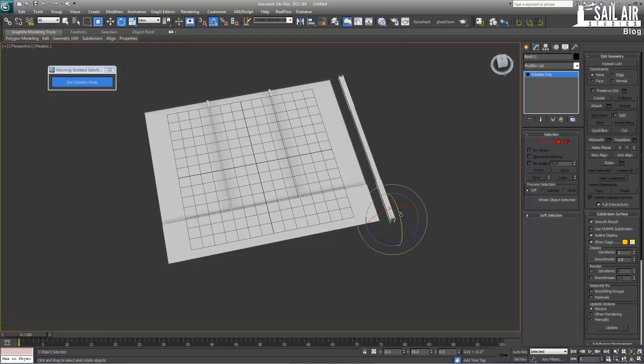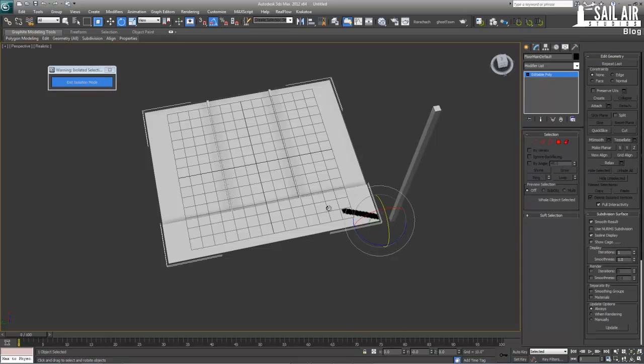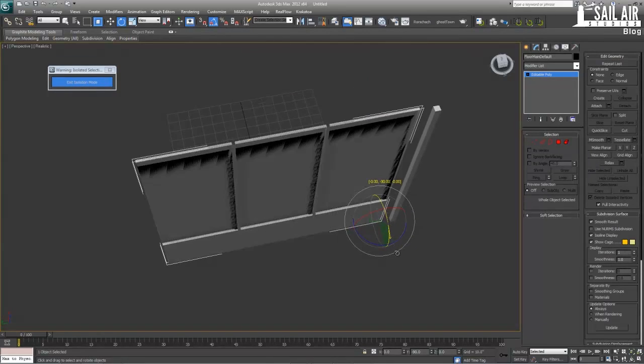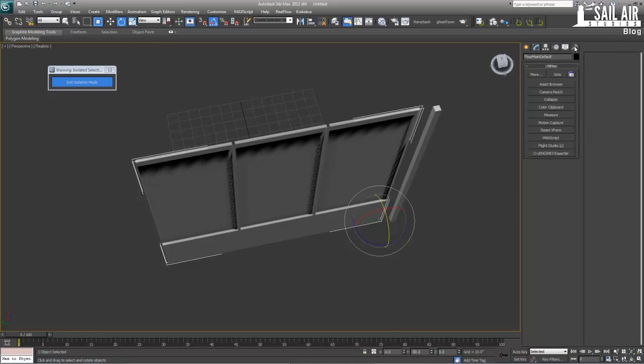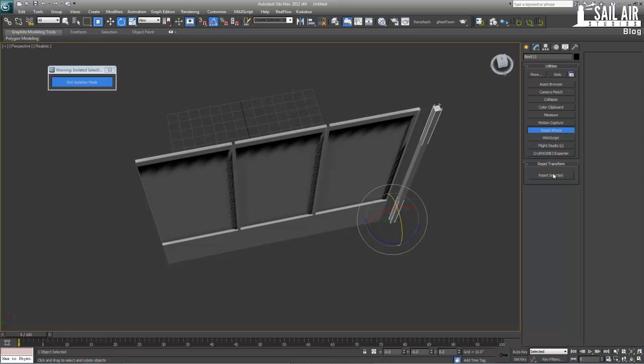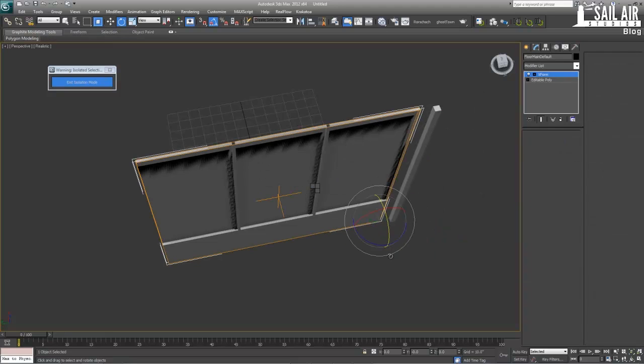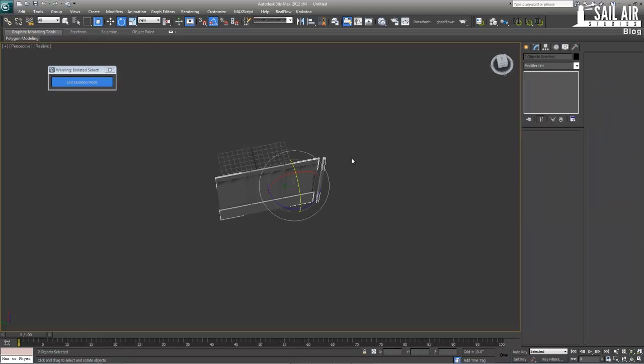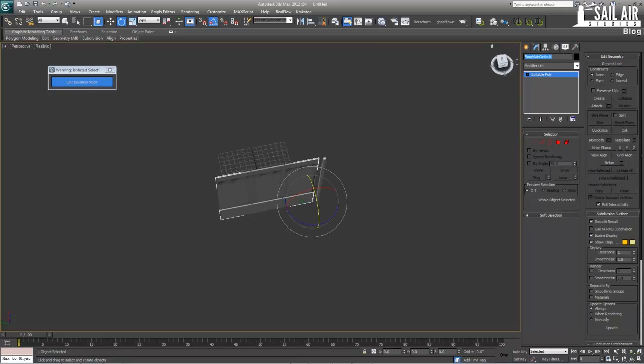Now what we're going to do is rotate them up to 90, or into the way they're actually going to be placed out. This zeroes it out. However, for this one, when we rotate it up to 90, you notice that this transformation stays there. There's also a movement transformation. So what we want to do is go under our Tools, Reset XForm, and Reset Selected. We do the exact same with this one, reset selected, and then collapse this. All we do to collapse is convert to an editable poly again, and you can see it gets rid of it. Convert to editable poly, gets rid of it. And these are our 2 things that we will be using in the RailClone: floor main default and floor main evenly.